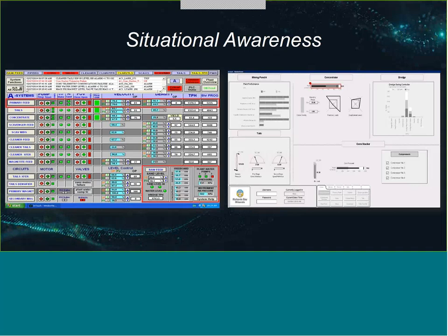And they're not static graphics, so they use something called symbol wizards. So when you drop them on the screen, you can choose how they look, the orientation, whether it has alarm limits, things like that. The key point about this slide is that both of those screens are identical. On the left-hand side, we've got exactly the same information as on the right-hand side. There's an alarm on both. It's very, very easy to see where that alarm lies on the right-hand side, whereas it isn't on the left-hand side in that very busy, colourful screen.